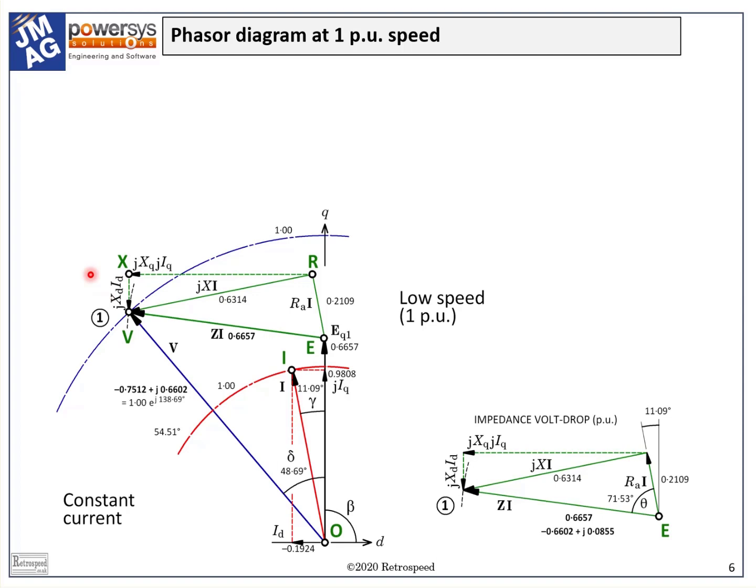I mention Blondel because in modern times we can calculate the d and q-axis components of flux linkage using finite element methods very accurately, even under highly saturated conditions. In that calculation we use Park's transformation for the currents and flux linkages, but in textbooks and even in Park's original presentation, there is a very complex process in which the phase inductance matrix is diagonalized and, in ideal theory at least, relieved of its troublesome dependence on rotor position.